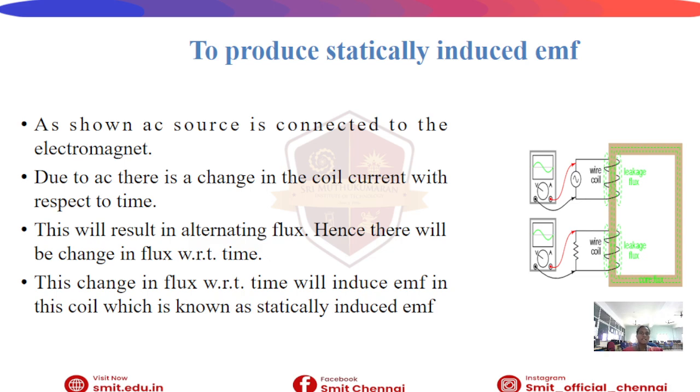Production of statically induced EMF. In this case, an AC source is connected to an electromagnet. Due to AC, the current changes with time. The magnetic flux also changes with time. This changing flux induces EMF in the coil, which is called statically induced EMF.